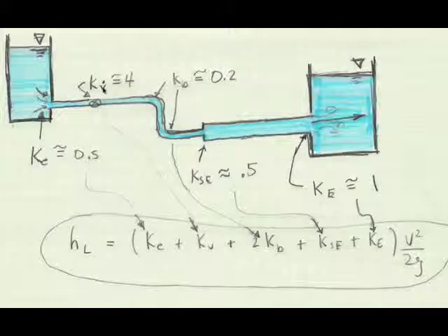When we want to do calculations, it's very simple. We add up the minor loss coefficients for each component in transition and multiply it by the velocity head. Then we add the head loss associated with flow in pipes by using the Darcy-Weisbach equation. In summary, the 1-minute concept is a tool for explaining concepts to other people.